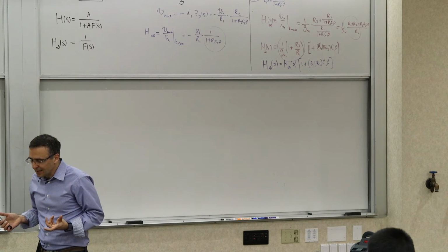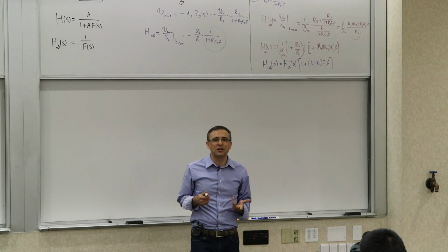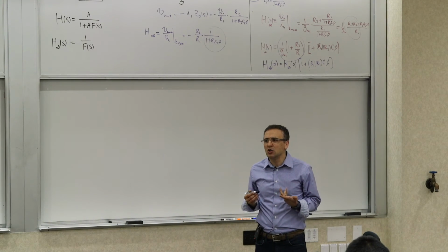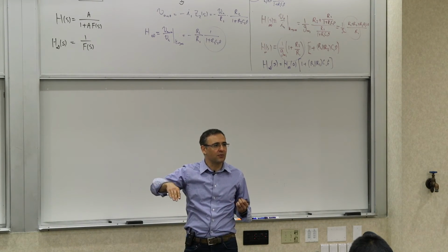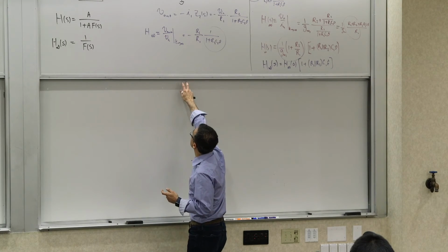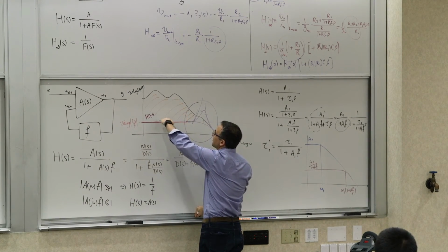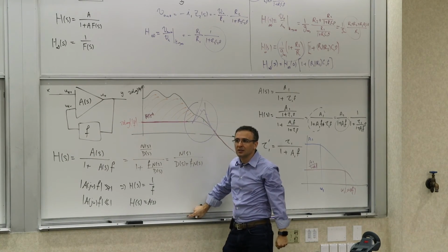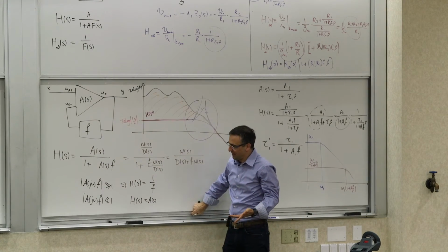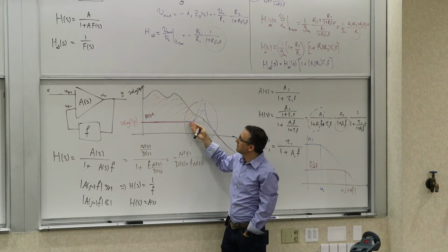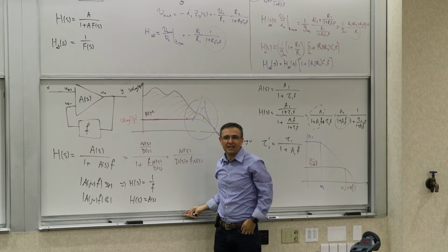So one of the things is that, okay, what good is feedback? Because we said, okay, the way you're achieving something is by reducing the gain where you had too much gain, for example, right? I mean, when you're looking at these transfer functions, we said the way we are really gaining something is by just killing the gain here and making it lower. Is that all it does? This is not a massive thing. I mean, it's a convenient thing, but what it's really doing is just lowering the gain here. Not doing anything magical.